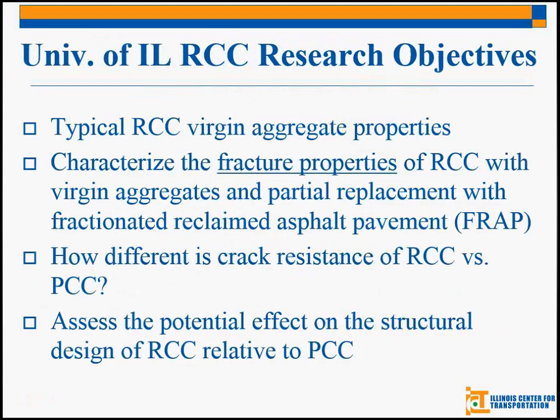All right, so that brings us to what we actually did here. We really wanted to get up to speed with RCC, try to get our own properties, get our own feel for how the material responds, and we also wanted to run our own fracture properties to relate back to that pavement design question of, do we actually need a thicker or thinner RCC pavement in relation to conventional paving concrete? Again, if we're using a thicker RCC pavement, we're negating the benefits of having a lower cement content because we have a thicker pavement. And so all of these are questions that we were hoping that we could shed some light on as we went.